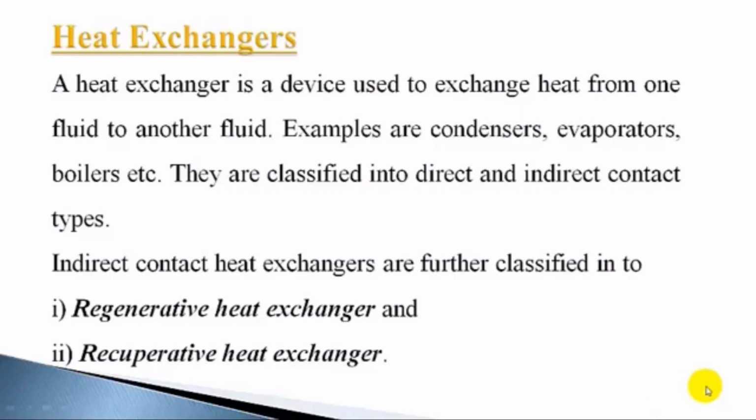In regenerative heat exchanger, fluids flow intermittently over the same area and exchange heat. When the hot fluid flows over the packing material used in the flow passage, it retains heat, and later when the cold fluid flows over it, it absorbs this heat. High thermal capacity materials are used to store heat in this type of heat exchangers. They have limited applications.